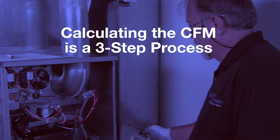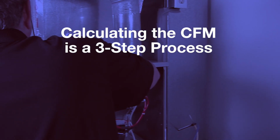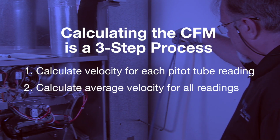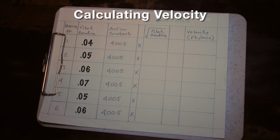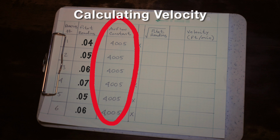feet per minute. Calculating the CFM is a three-step process once you have completed your airflow measurements. Calculate the velocity for each individual pitot tube reading, calculate the average velocity for all the readings, then use that average to calculate the airflow, or CFM. To calculate individual velocities, take the square root of your pitot tube reading and multiply it by the airflow constant. The airflow constant is 4005 and can be found in the air properties and measurement materials.